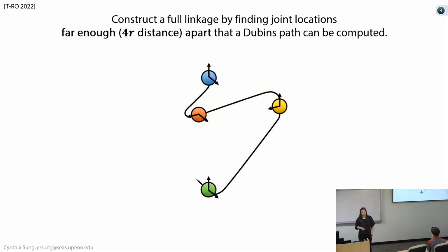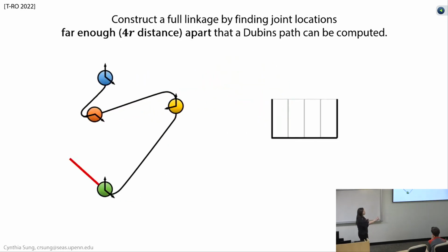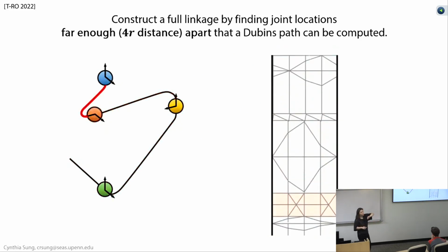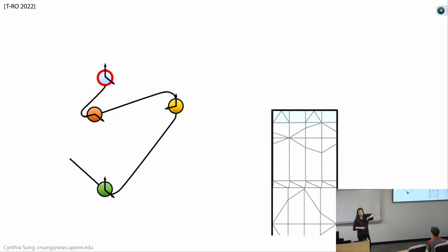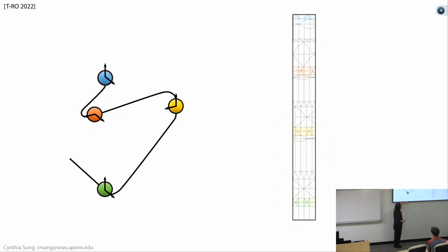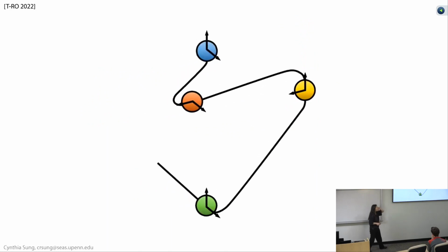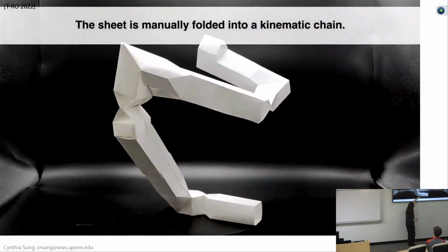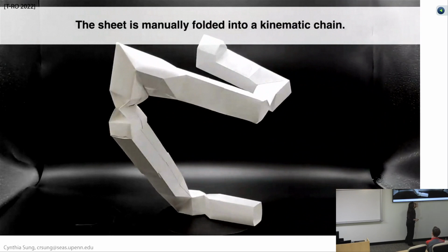And so what you're seeing here is that process of moving the joints farther apart, and now every component of this path is being converted into the corresponding fold pattern, which then folds into a 3D structure that basically follows this path. So what you're seeing now is the equivalent folded mechanism. And these parts here, this one, and that one, are the rotational joints. And their axes of rotation are in exactly the right place according to the original specification.